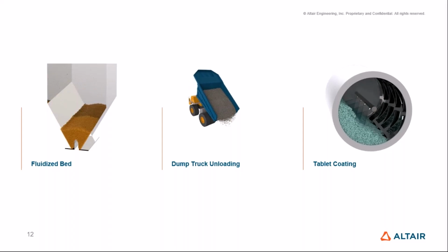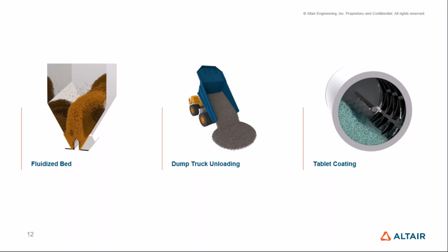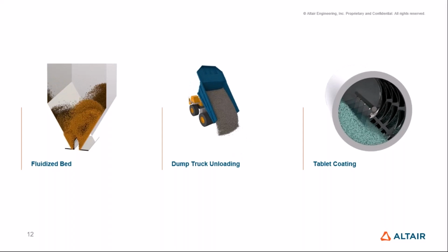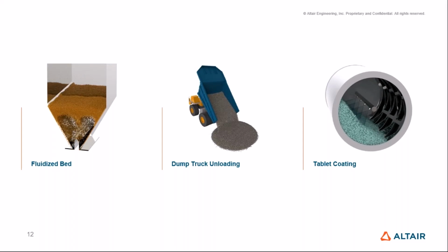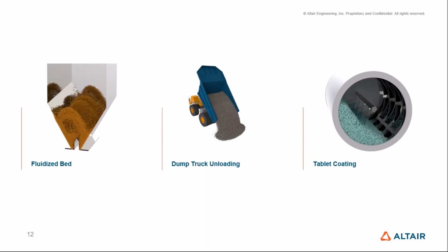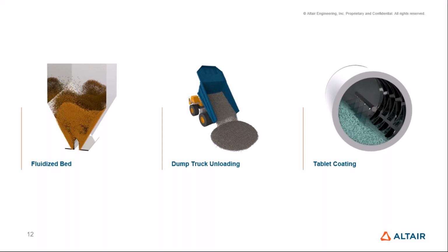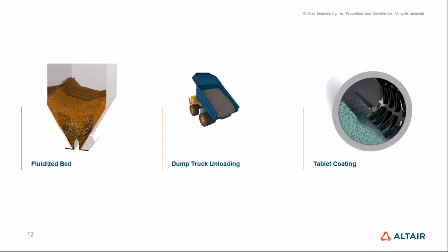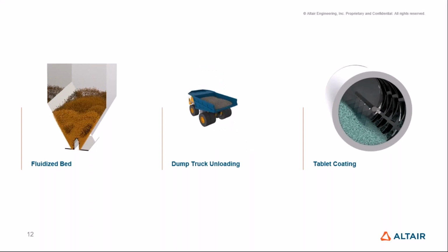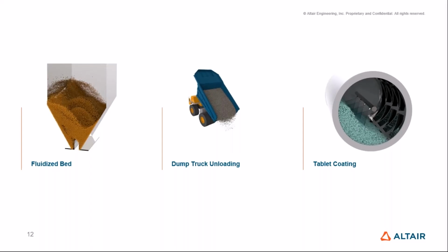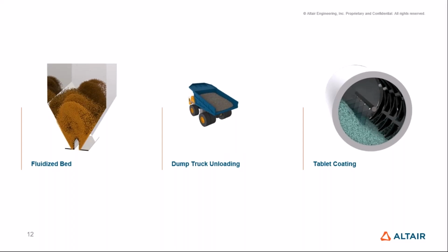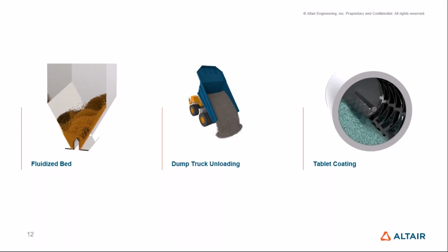You even have little tricks, like in the case of the tablet coating. Here, revealing all my secrets at the moment. In the case of the tablet coating, for example, the way that this simulation was run was to highlight the new ray tracing post-processing capabilities for coating, which allow us to get the intraparticle coating profile just in post-processing. So for the visualization of this one, what we did in this case was create literal cones as geometries directly inside Inspire Studio.